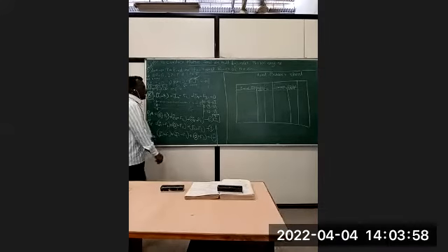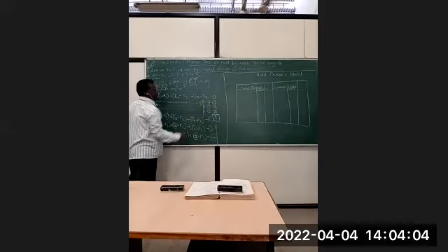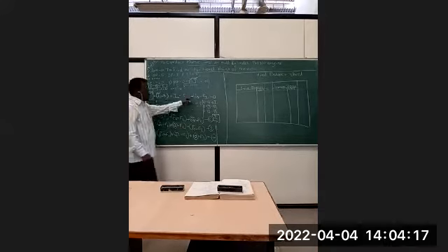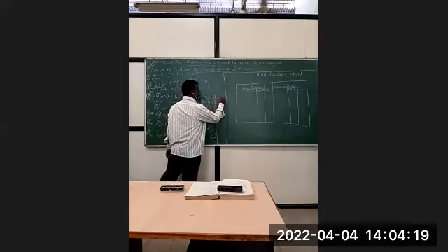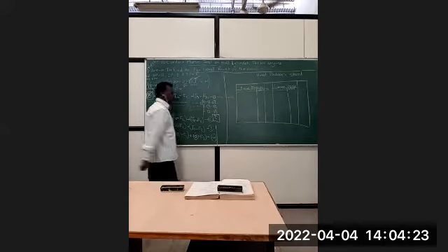Now, what is the concept here basically? Initially we will be running the first test. That is, when all the engines are running, all the cylinders are working, all the spark plugs are firing, we will have a brake power. Suppose we take this particular test at 2000 RPM.